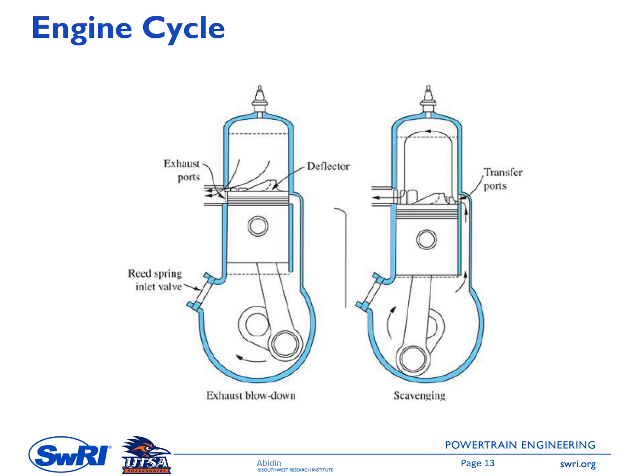Now let's take a look at the two-stroke engine. This figure is showing the schematic of the two-stroke engine. In a two-stroke engine, one complete cycle is done by just 1 crank rotation, and the compression and the expansion process, or the power stroke, are the same as the four-stroke engine. The difference is in the intake and exhaust strokes.